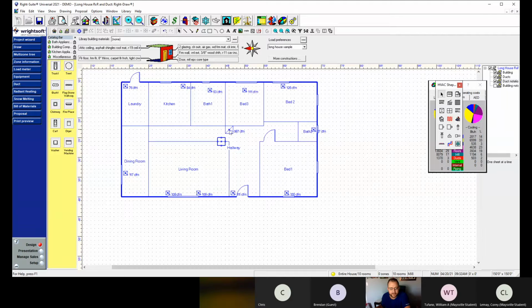So most of my supplies I'm putting toward the outside, so I can create kind of a circulation. And I'm going to put my returns more in the center. You can do a central return, or you could come in and do room returns. And in that video, you're actually going to see me kind of do this again.